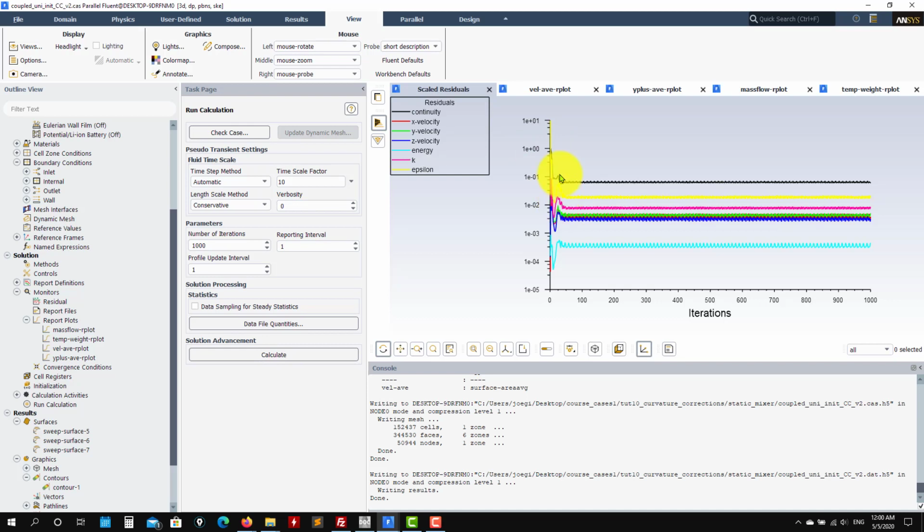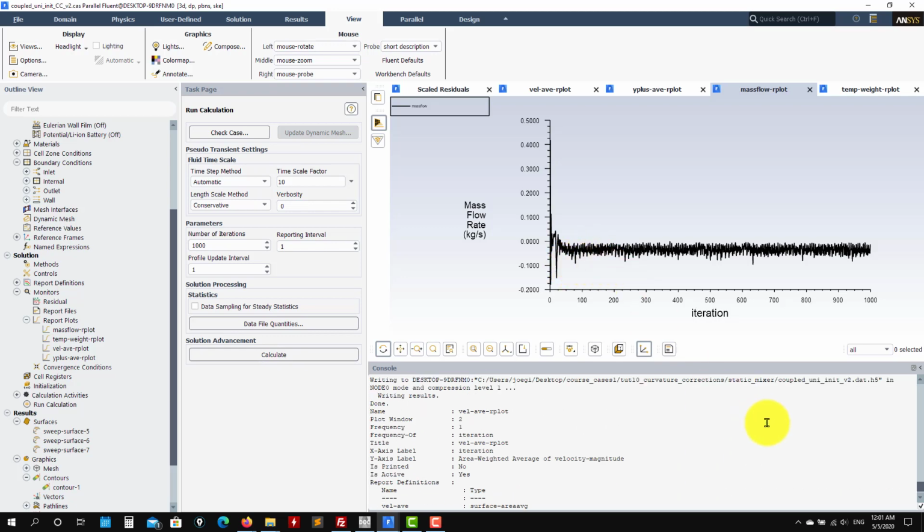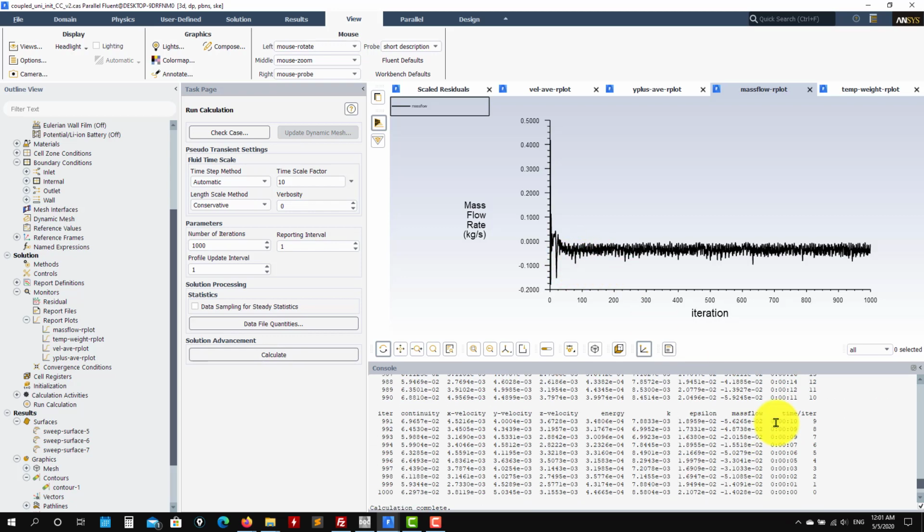Okay, so we start to see that you increase your, let's call it, fictitious time step, but that is not giving you any benefit in your solutions. So it's not a good choice to go very large. Again, if you see that this behavior is no good, you reduce it. But also what is interesting, look at the mass flow, it is not perfectly balancing. It's a small value, but it should be much closer to 0. So you have some conservation problems.